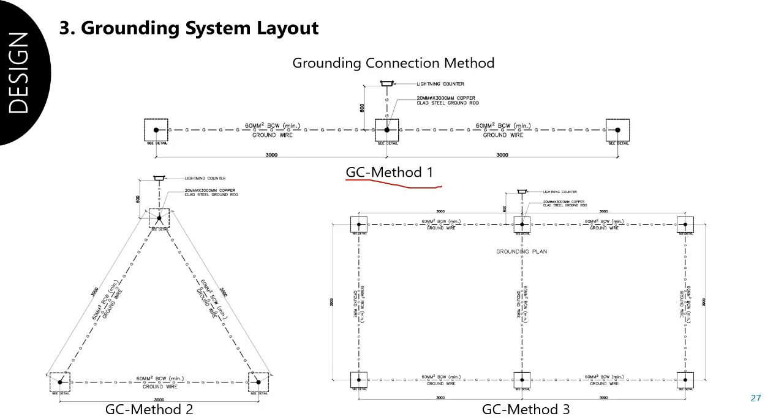What I prepared here is, in most of my project installations I use the triad design. The main reason I prefer the triad is that if there is a problem, let's say the ground wire is cut, ground number 1 is still connected, 1, 2, 3.